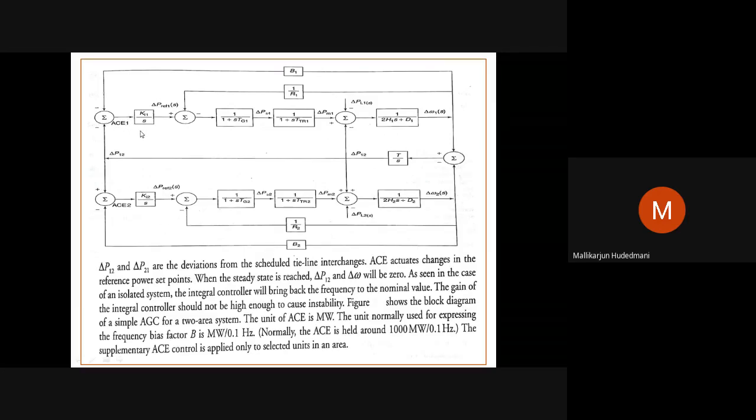This is the beauty of interconnected operation. ACE value plays a great role in the energy control center. In the energy control center, with computer controlled generation, the ACE values of area 1, area 2, area 3 load centers are usually used to transact power among the corporations. Who is selling, who is buying, who, at what time, like that. ACE value defines their transaction. ACE is a very important aspect of interconnected operation of systems in real time.